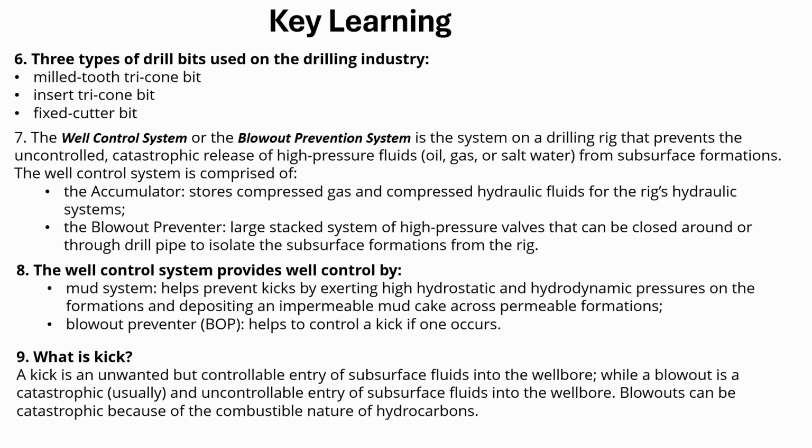A kick is an unwanted but controllable entry of formation fluid into the wellbore. A blowout is the uncontrollable and catastrophic version of that event. This distinction is crucial. A kick is a warning condition that still allows intervention. A blowout represents a loss of well control with potentially severe consequences, especially because hydrocarbons may ignite.